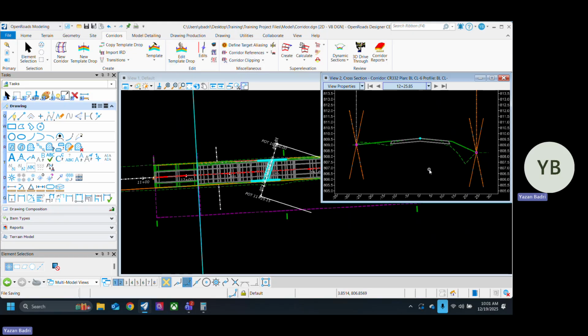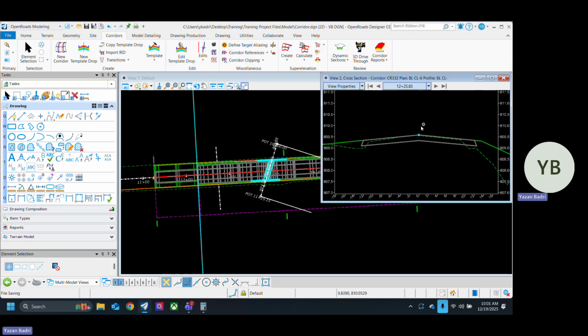So we need to get the existing centerline profile as close as possible, right? We didn't really do that here. We just did something close, but it's not exact. So we would want to be more precise and get the actual existing profile. That way there's nothing below the existing. It's just at the existing. Looks like the existing is even less than 11, less than 12.